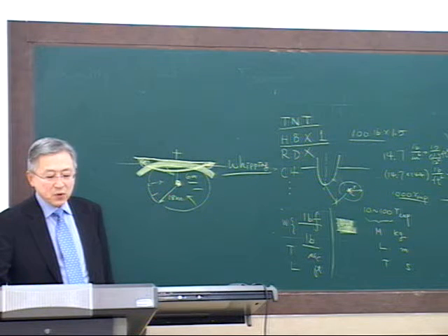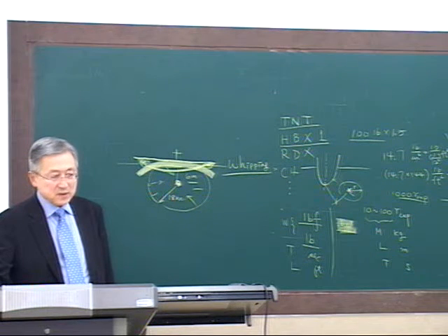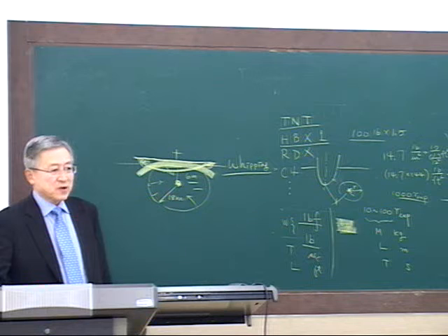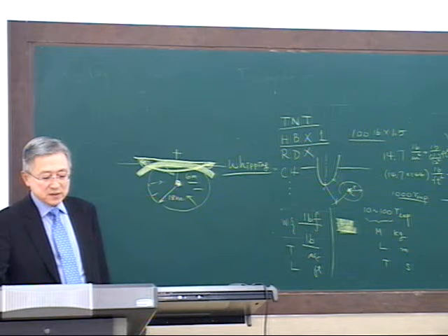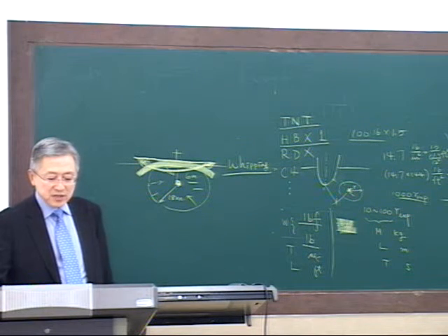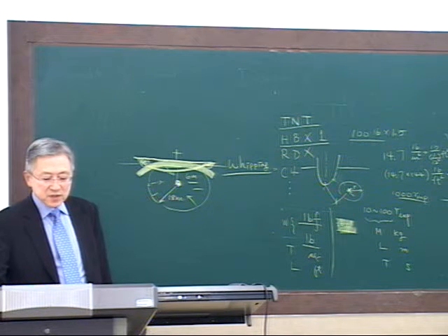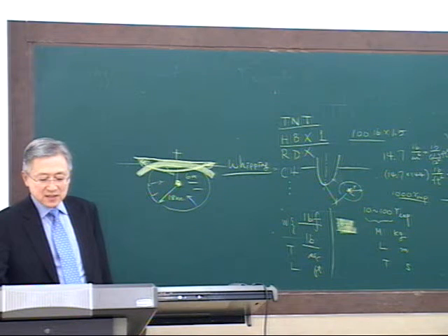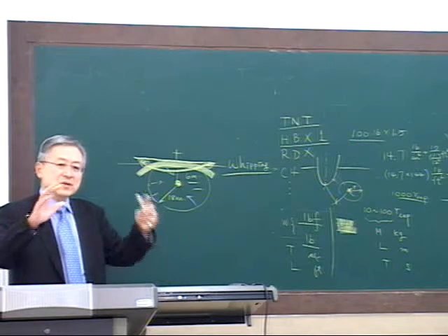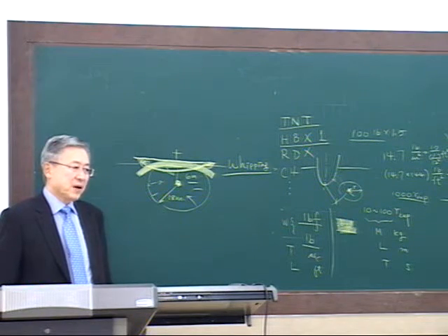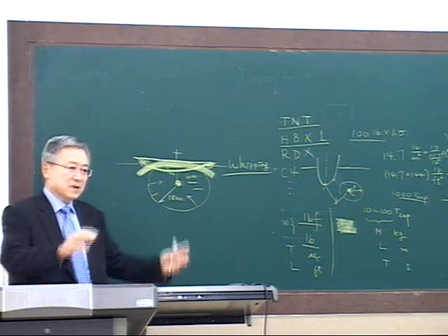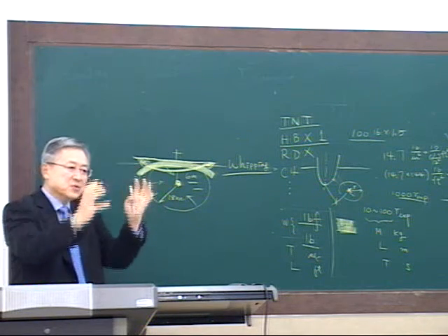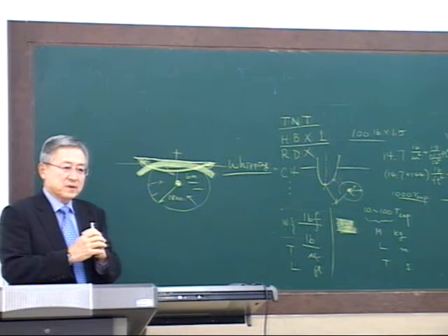This is the vertical momentum of the gas sphere with the particular rising velocity u, whatever the bubble velocity is. And m_a here is the added mass of water, which some people call hydrodynamic mass, due to the drag forces or viscosity of the water, which is the pulling effect on the gas sphere.